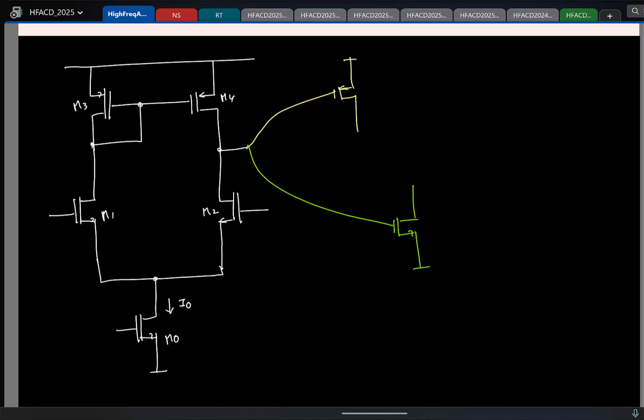Yeah, okay, can you explain more? You're saying you're getting higher output swing in NMOS. Why? Okay, maybe I'll do it this way. Let us say I look at the first stage. Both are biased at the same bias voltage, because in negative feedback the two terminals will be at the same potential. Then what can you say about this VD1? What is VD1? VDD minus VSG3 at I0 by 2 current.